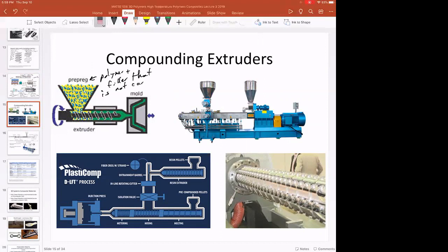Let's get cured, right. So you can have a thermosetting composite, and this will be thermoset molding. Sometimes this is called compression molding. You don't really want to thermally extrude a thermoset because it's going to cross-link in the extruder, but you still use an extruder to pressurize this thermoset into a heated mold, and then you get a molded part.